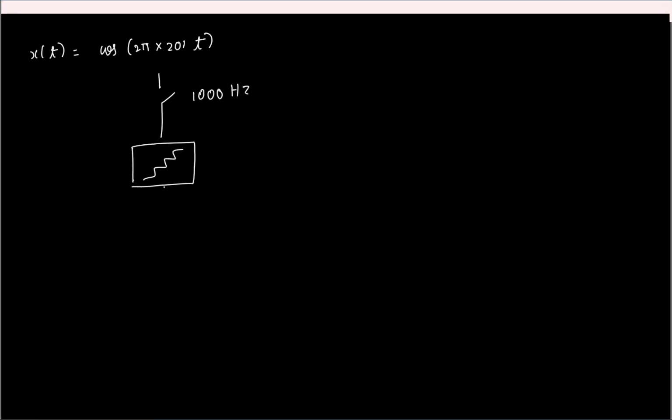But of course we don't deal with ramp signals. So I took sinusoids because any signal you can decompose into sinusoids. So let's say I take a sinusoid, say with a frequency of 201 hertz. I sample it at say 1000 hertz. Again I quantize it, and let's say I take 1000 samples of this. So the sample size is 1000 here. And then I do the same thing, find the quantization error and then plot its histogram.